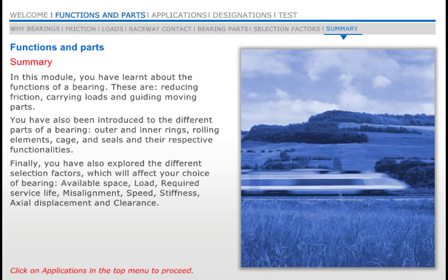Finally, you have also explored the different selection factors which will affect your choice of bearing: available space, load, required service life, misalignment, speed, stiffness, axial displacement, and clearance.